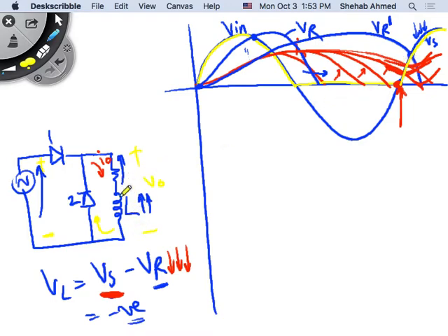But the inductor voltage is negative. Remember, we're in the falling. It's falling, so inductor voltage is negative. VR is a small positive value. There will be a small opposition to diode 1 turning on. Yeah, right. Inductor voltage is negative, and this is a small positive number, so this is helping diode 1 turn on. Right? So as soon as diode 1 has an opportunity to turn on, it will turn on.